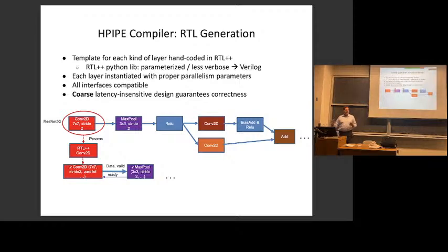We can compute, maybe through the next 30 clock cycles, what we need to do to produce a bunch of outputs, and there's no possibility that we'll have to stall or that we'll generate invalid data. So we use a very simple streaming model that can't be stalled inside of these blocks, and a more complicated one that can be stalled in between them, and lets us compose them all together.